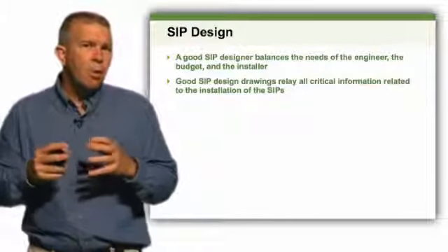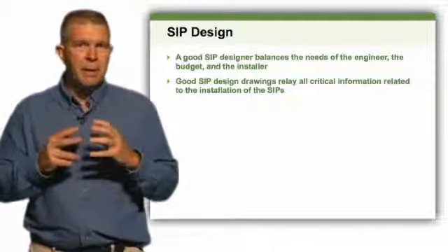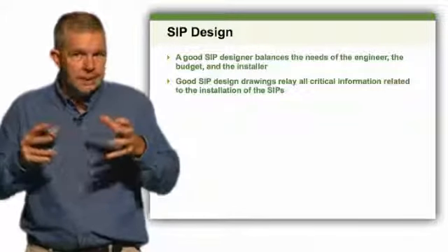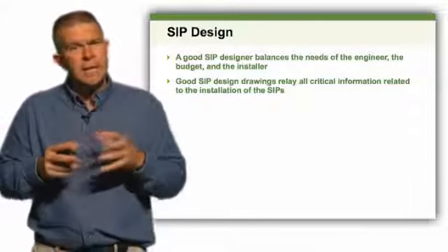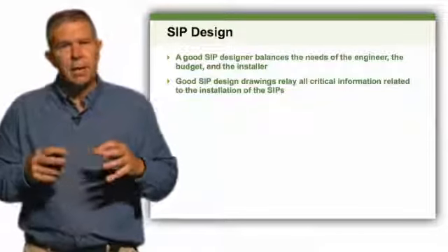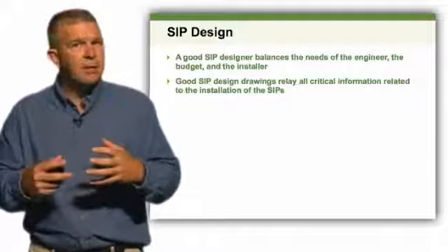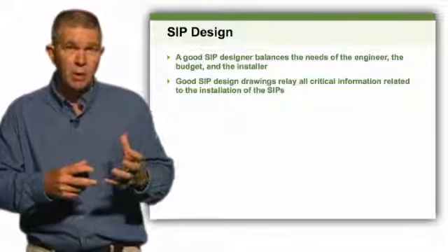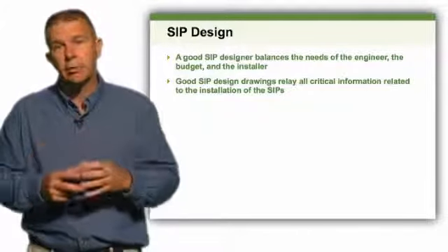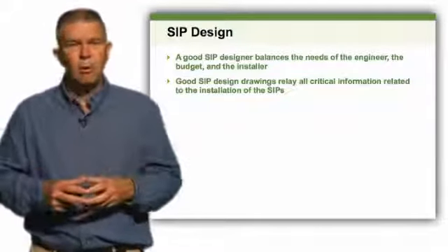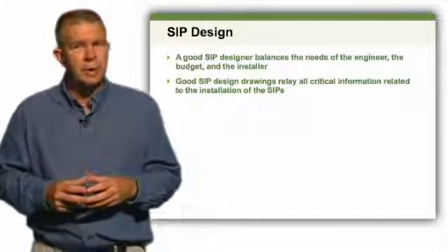As they put all of this knowledge of SIP engineering and design possibilities together into their design drawings, they need to create a set of drawings that relays all of the critical information, that is the details, the sections, and everything combined with the engineering requirements, so that we have a SIP panel layout drawing that then allows us to move forward. And we're going to talk about SIP panel layout drawings later in this program.